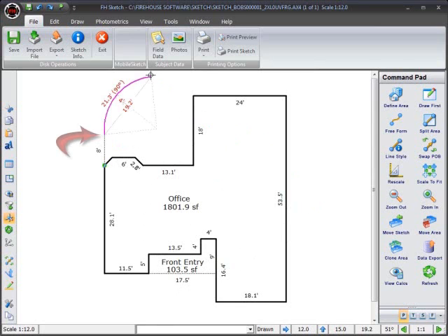When we drew the 8-foot line, we already knew where the curve begins. Looking at our notes, we also know the curve ends 13.1 feet to the left of this point. I can establish the chord by placing the cursor near this point, press J to jump to it, then enter 13.1 and press the left arrow key. Your curve is now positioned, and you can anchor it just as we have with any other line.